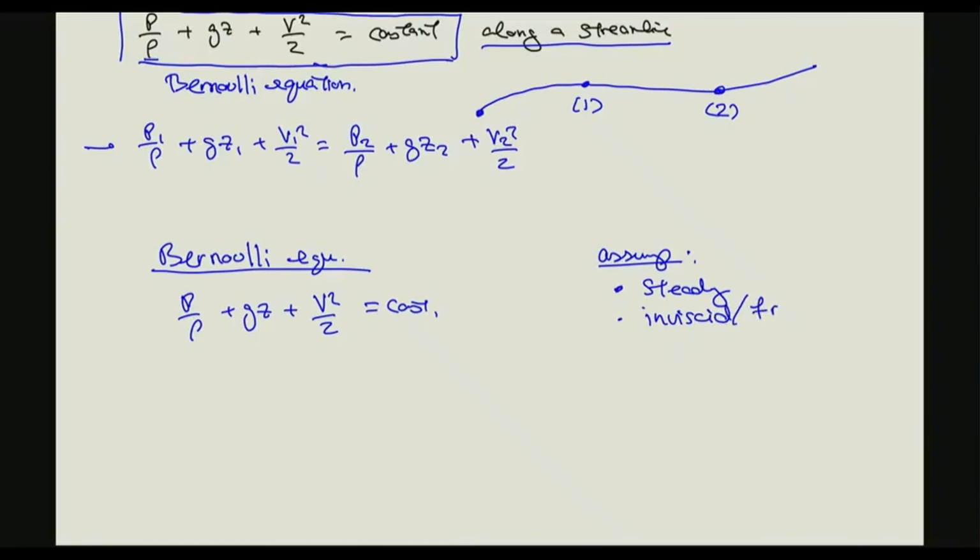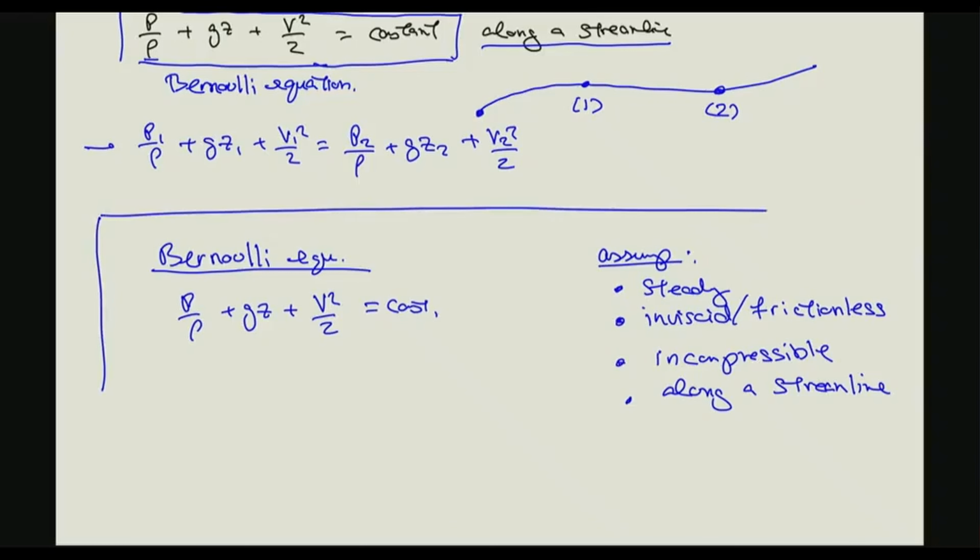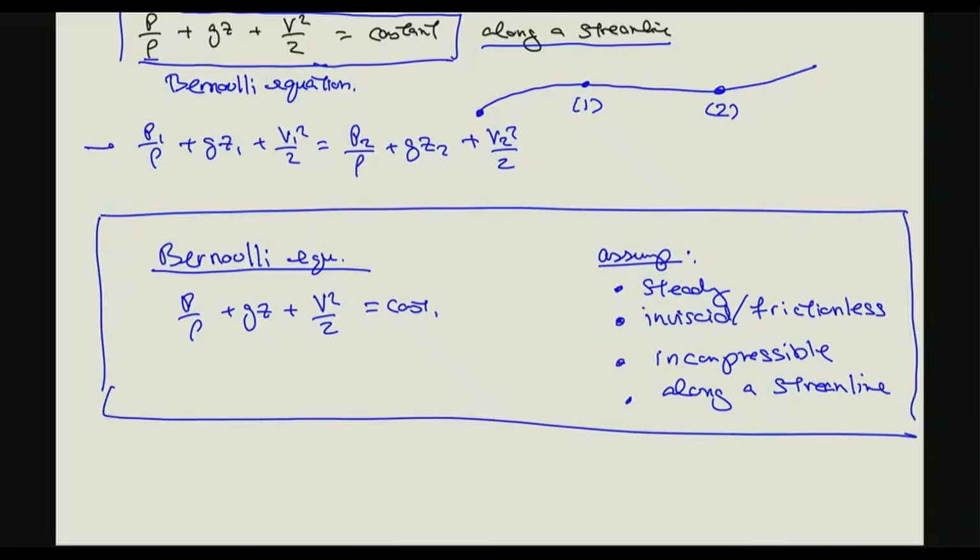Inviscid, sometimes we just refer to it as a frictionless flow. Incompressible, and along a streamline. So, very restricted, okay, but easy to use. And so it's often abused.